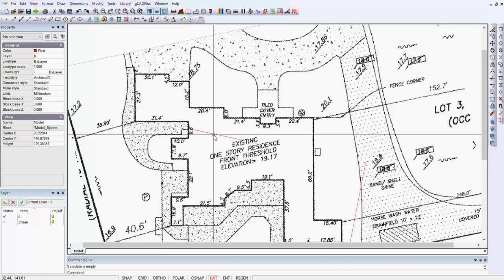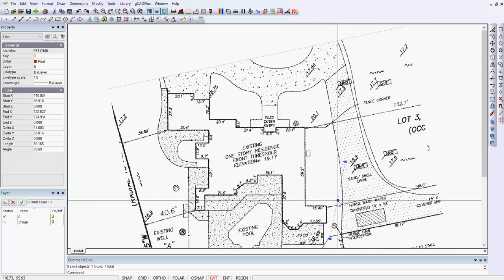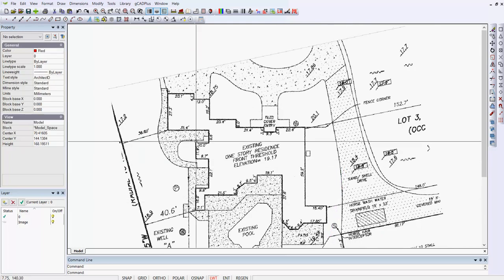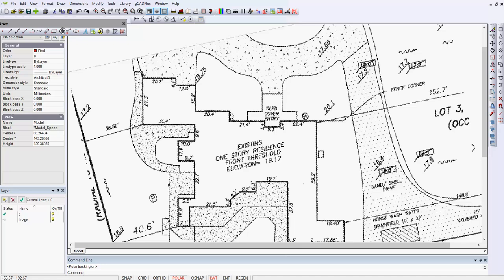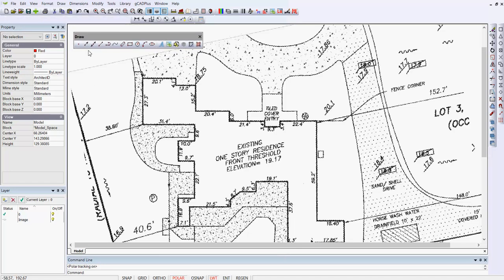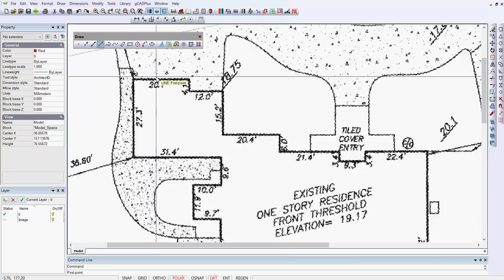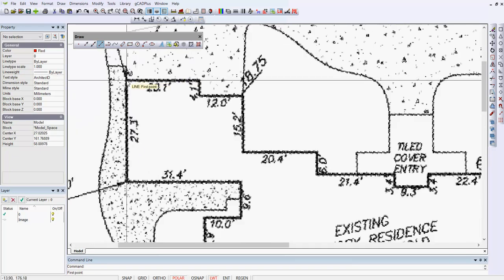We didn't rotate the line, of course. Let's delete that. It was only a fudge line. So now, and I'll get rid of this one as well. There were a couple of lines that I was playing with. So now we could turn Polar on, start our line again, and I'll float it for the moment just to show the standard toolbar, draw a line, and we could come in here and start clicking, so I can head off in that direction.